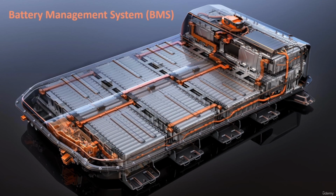To secure a long cycle life, safety and optimal performance, the current and capacity distribution over the individual cells needs to be regulated. This is achieved by the Electronic Battery Management System, the BMS. The BMS continuously monitors the voltage, state of charge, and the current of the individual cells in the battery pack and is able to regulate how individual cells are charged and discharged. One of the important roles of the BMS is to balance the state of charge of the individual cells.